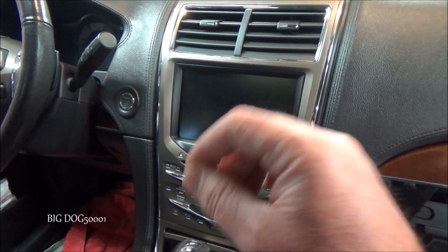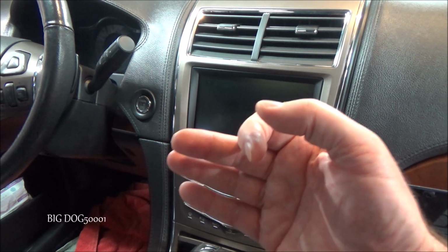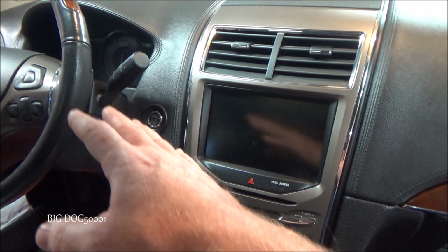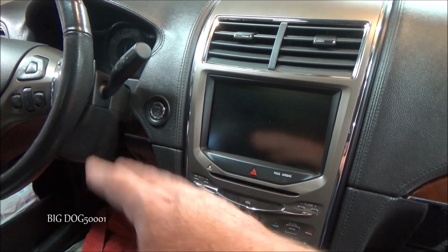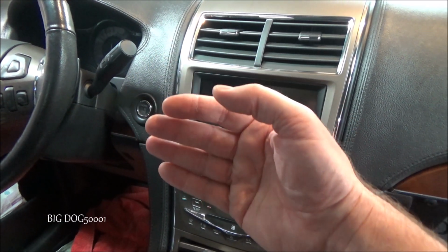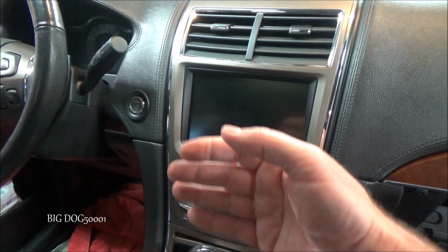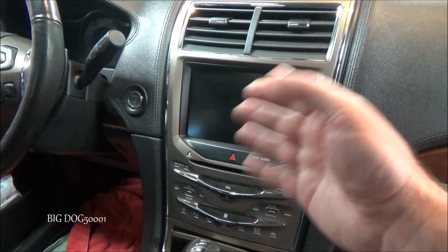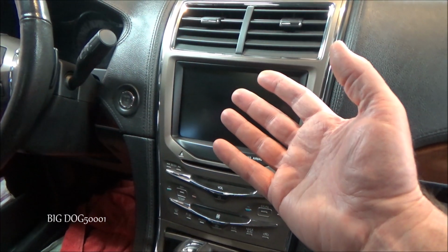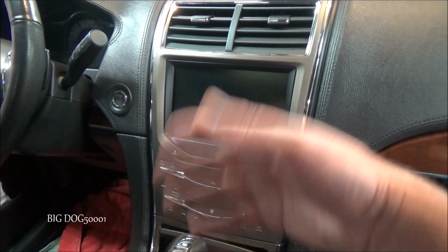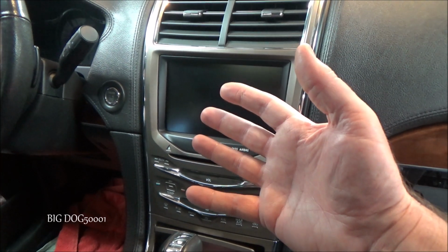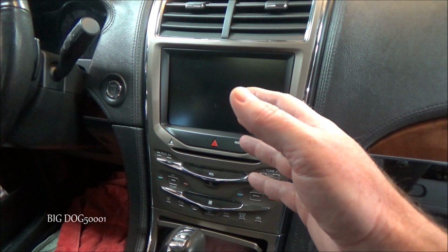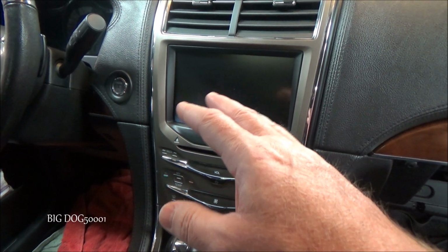We need more details. If it's wintertime and the complaint is no heat on one side, but there's plenty of heat on the other side, then I'm going to at least verify that our coolant level is correct, that the whole cooling system looks good, and that we don't have air in the system. Especially, hey, did we just work on the cooling system? Did I just drain the coolant and refill it? Maybe there's a big air pocket in there and that's what's causing our issue. So once again, I'm trying to think logically to fix the problem.